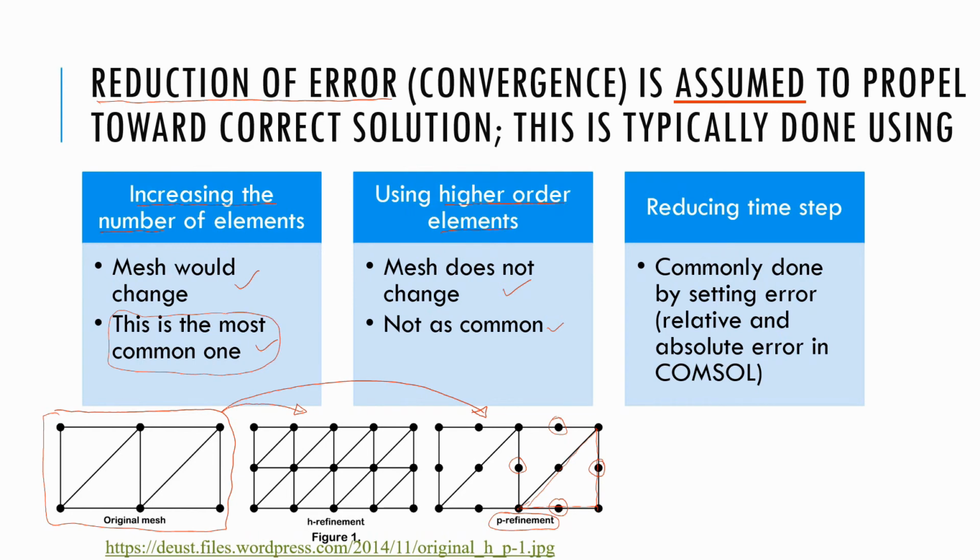Now both of these together reduce the spatial error, and then we can also reduce the error due to the time stepping, and that is commonly done by setting error tolerances, just like the example I showed in the previous slide.